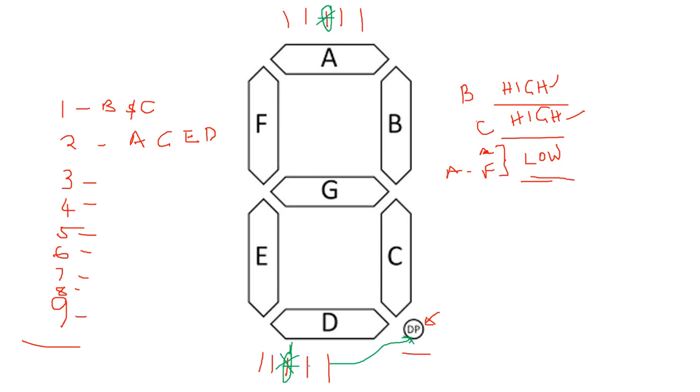You can try it live: connect this to a positive power through a resistor, then take another jumper wire from 5 volts, or you can ground that, and when you touch this pin with the wire, you'll see which LED lights.